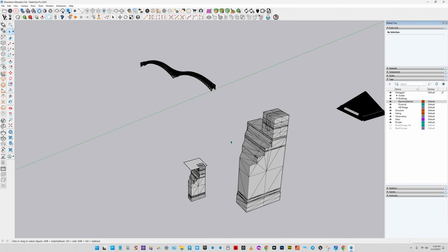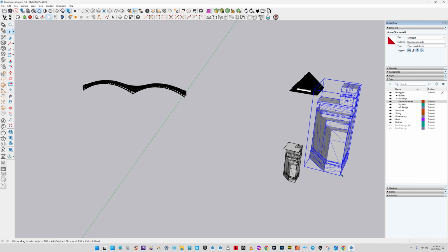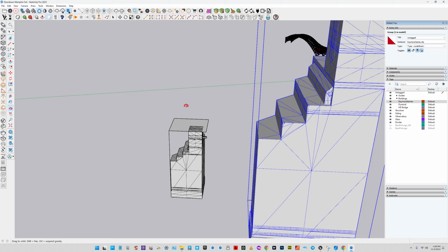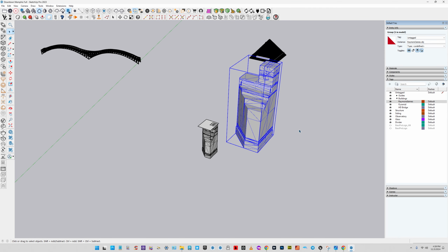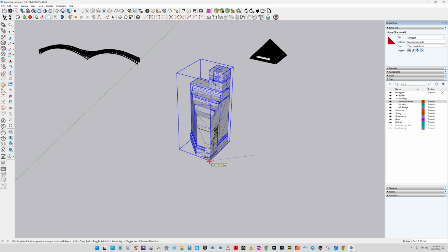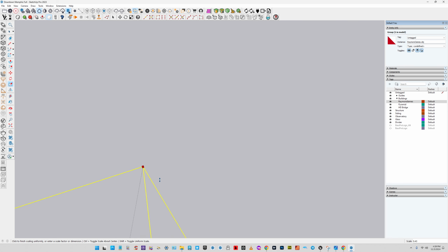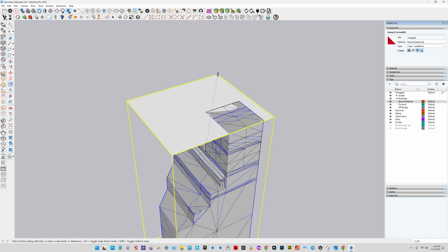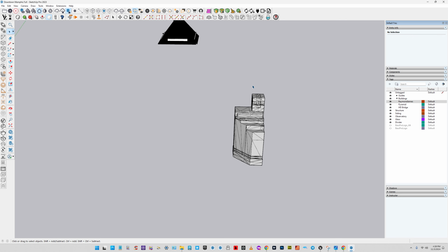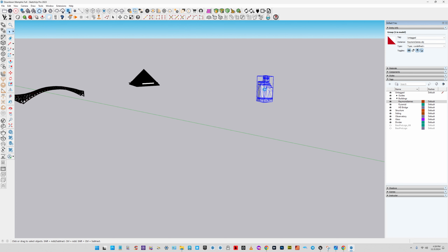And now I should be able to move my OBJ import, seeing that the bounding box is now encompassing the edges of all these rectangles I had created earlier. We can now move this from this corner to here and then do an appropriate scale down to this plane that we created. All right, and then we can delete the STL import, and now we have our OBJ version imported and scaled properly.